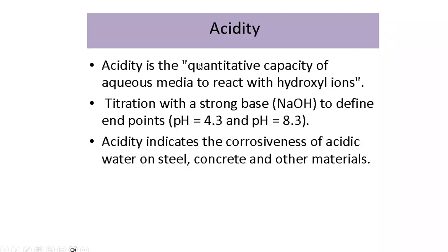Acidity is the quantitative capacity of aqueous media to react with hydroxyl ions. Titration with a strong base, NaOH, is used to define endpoints: pH equal to 4.3 and pH equal to 8.3. Acidity indicates the corrosiveness of acidic water on steel, concrete, and other materials.